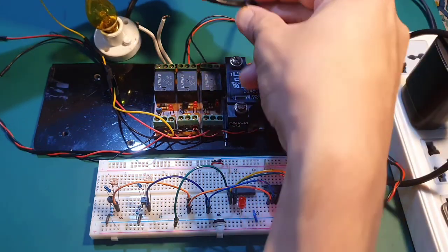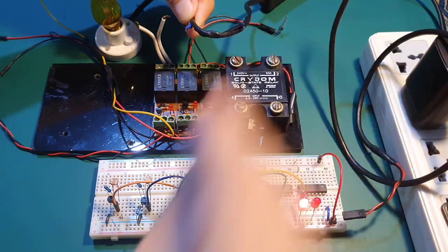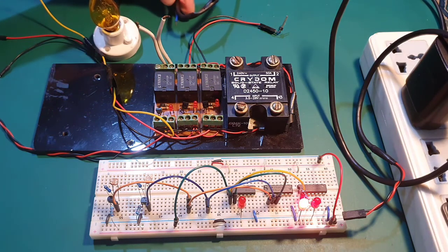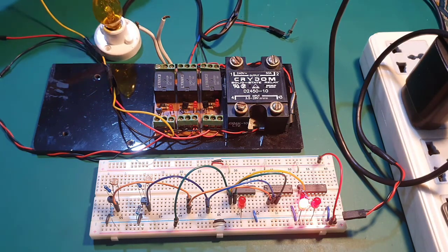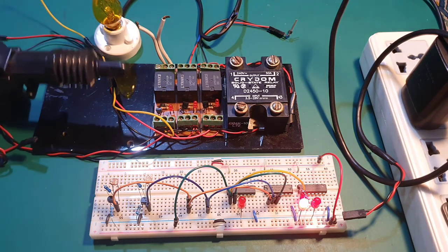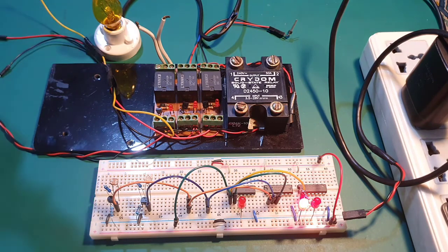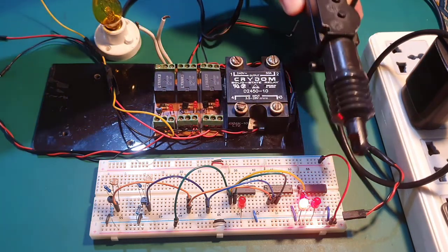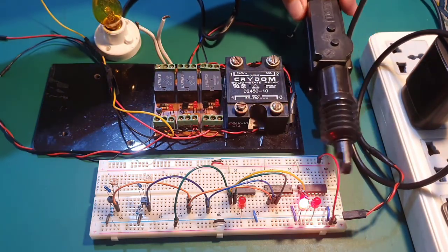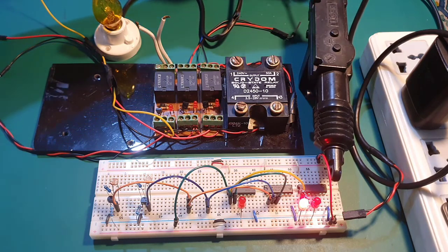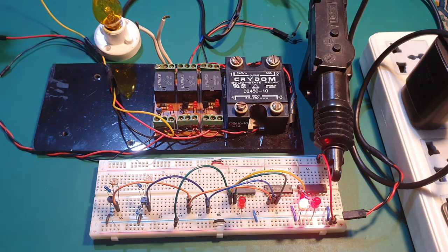However, our light bulb requires a higher voltage of 220 volts and a higher current, more than enough to get you electrocuted. In addition, although the push-pull solenoid that we use to lock and unlock the door only operates at 5 to 12 volts, the current it requires to energize the coil that generates the electromagnet is way higher as compared to the output current that our logic circuit can supply.